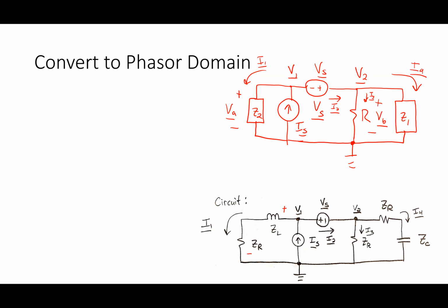Now, what I want to do for myself real quick is define, for all of my impedances here, my Ohm's law setups, right? So for me, I say, okay, I1 is equal to what as an Ohm's law relationship for me? What's I1?